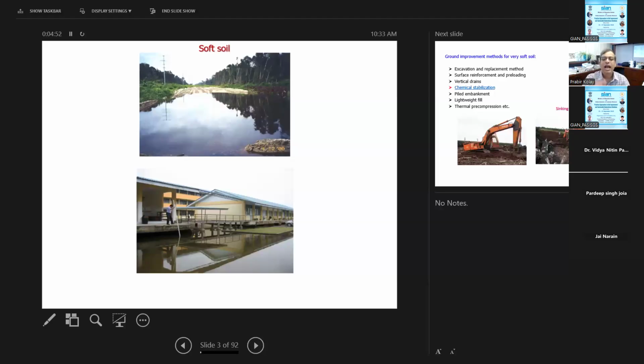It's so difficult. And I know there is a town in Malaysia, in East Malaysia, in Sarawak, on Borneo Island. Basically they constructed everything on piles, and everything is good. But the remaining structures, everything has settled. And that town is really abandoned now because of too much settlement. All the utility pipes and everything have settled, and people cannot use it.